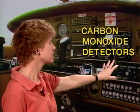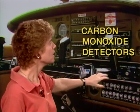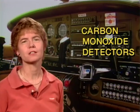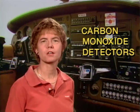Let's talk about fire and smoke detection, and the first thing we want to talk about is carbon monoxide detectors. Carbon monoxide detectors are found very often in the cockpit or the cabin of an aircraft, and the reason for that is that the cabin heaters on small aircraft are basically heat exchangers around the exhaust of the aircraft, and if they get a leak in them, you can end up with carbon monoxide in the aircraft cabin, which is a bad thing, and so some aircraft will have carbon monoxide detectors in the cockpit or the cabin.